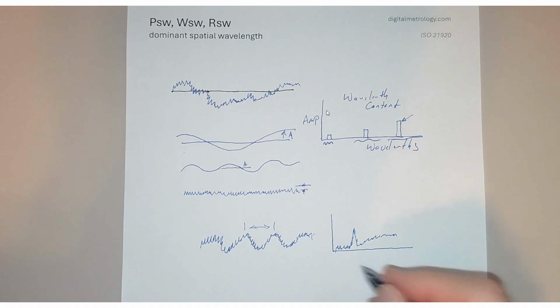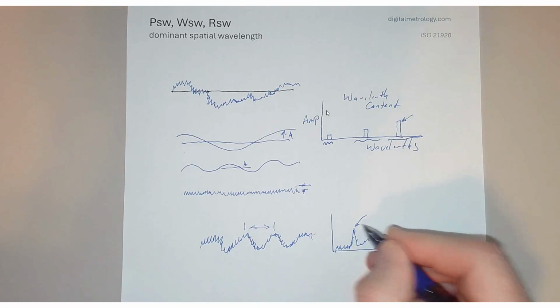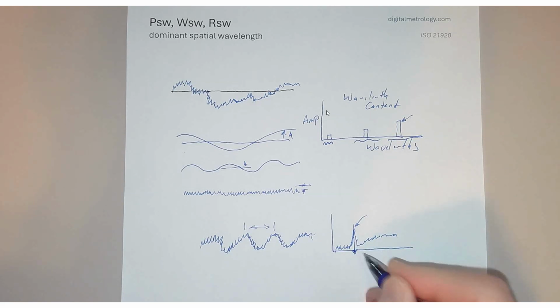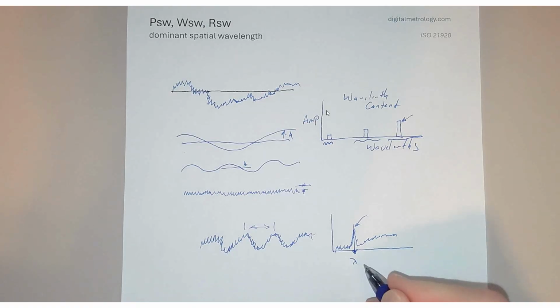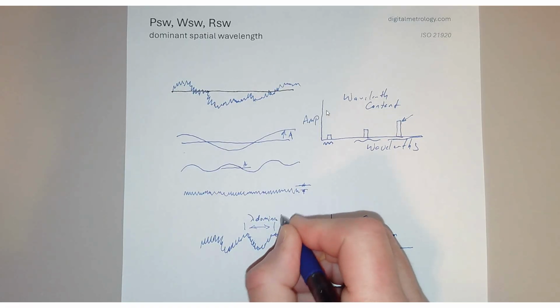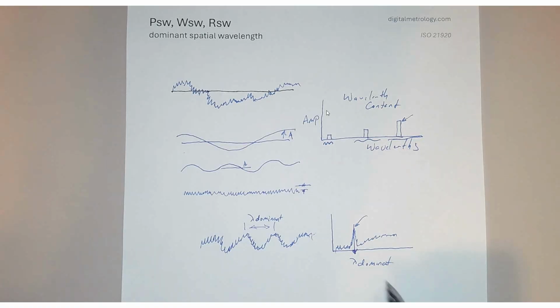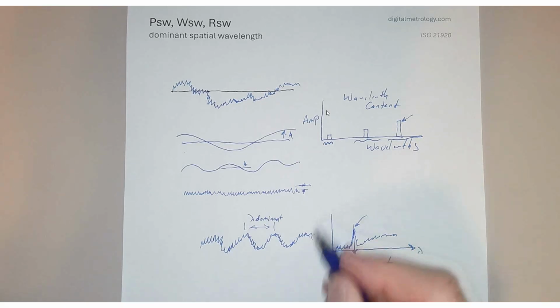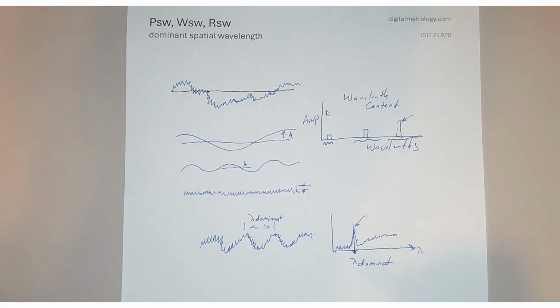This wavelength content graph shows a strong amplitude right here. The wavelength where that occurred is some wavelength that's dominating. There's a dominant wavelength in this surface, and right here is the spacing that's associated with that dominant wavelength. So this spacing is reported right here on the wavelength axis of the wavelength content graph. We can use this math to determine what is the wavelength that's showing through the strongest in a signal.